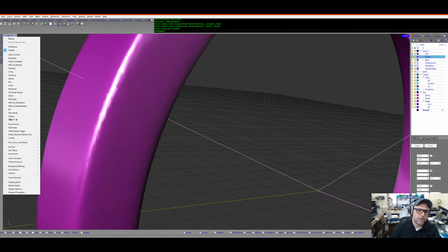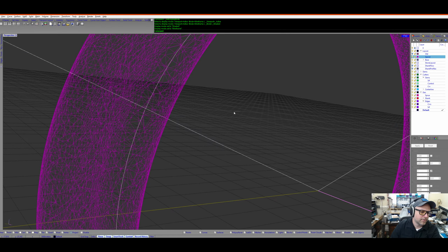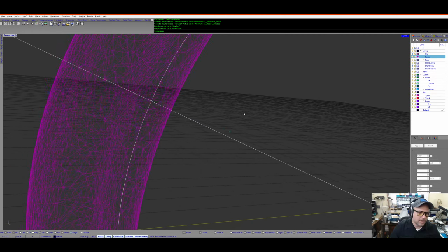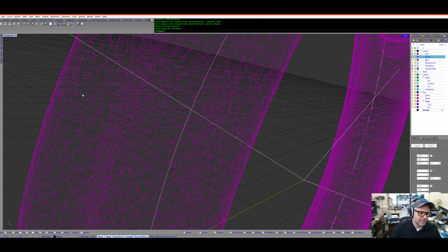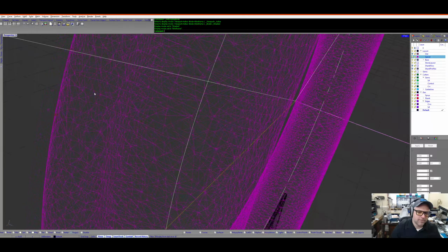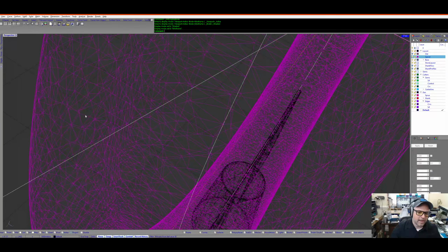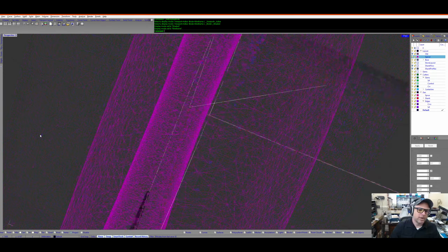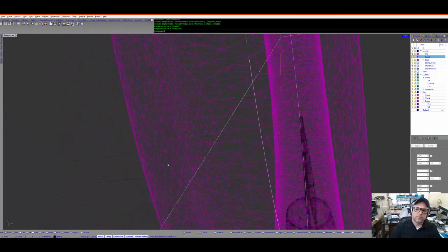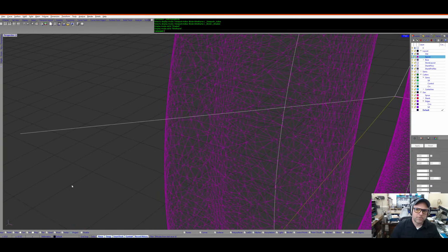Let's go back to the wireframe here. I'm not sure which part, because Juan, I missed that you asked that question, but sub D is 4-sided quad mesh, and I want triangles because some slicers don't like quads. They will only take an STL, which is 3-sided. They won't take an OBJ file with quads. So sub D won't do that.